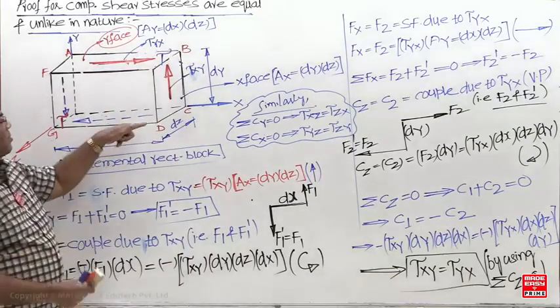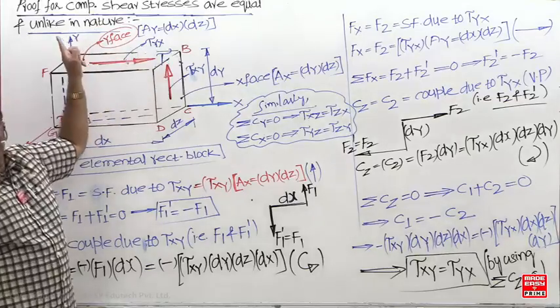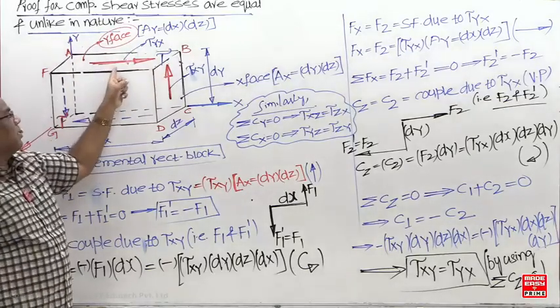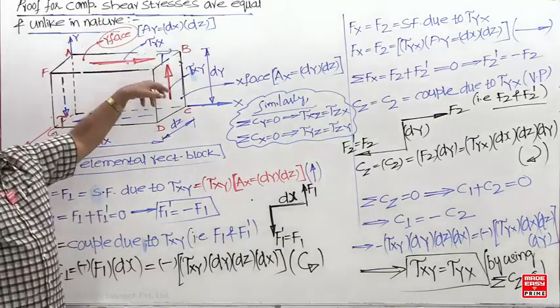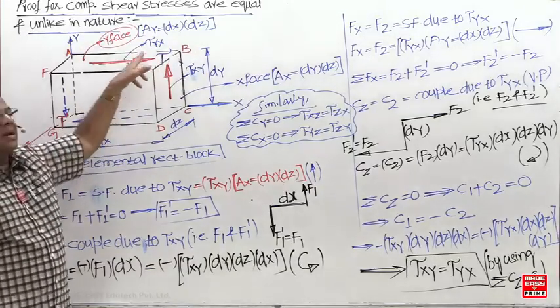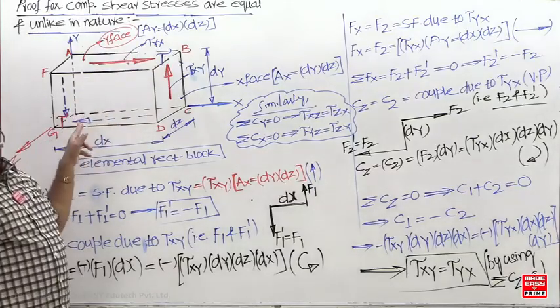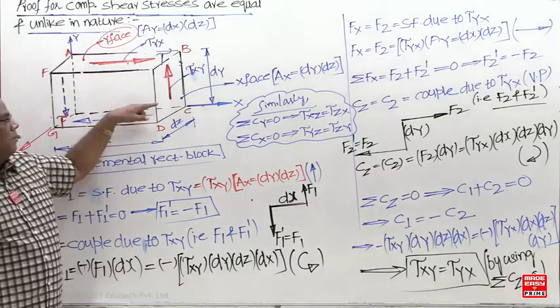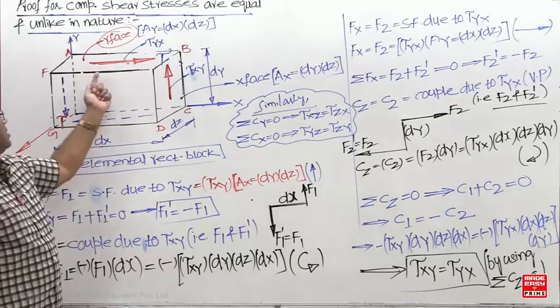So what is the tau xy value now? Tau, but negative or positive? No, negative, minus. And what about tau yx, also tau? This is going to be clockwise. So if I have written this, what numerical value is going to be there? What is the value now? Value is tau, but direction is anti-clockwise. Therefore tau xy equals minus tau, and this is tau yx.